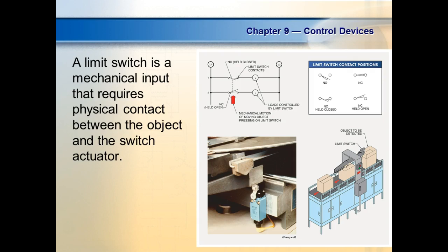You understand that? So this is what the limit switch is. Even though the limit switch is a proximity sensor, which means this guy is going to detect when something's at a certain spot, it doesn't know the position. All it knows is when it's at a position, right? Does that make sense? And these guys became known as limit switches because this is what they basically were originally used for.